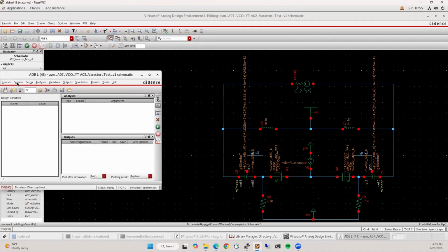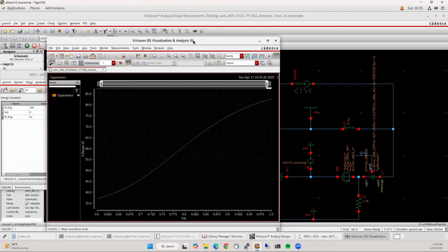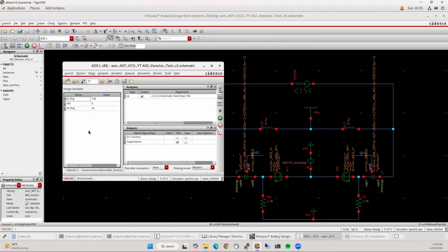So now what we'll do is we are going to load our varactor test bench that we had earlier. I can close this. Let's save that. And then we want to set some values here. So let's say 445 milli, that doesn't really matter. And for the varactor MIM and MOS, okay, I think the MIM cap should be large, so maybe we'll say 50 and 1 micro, 25 and 1 micro.